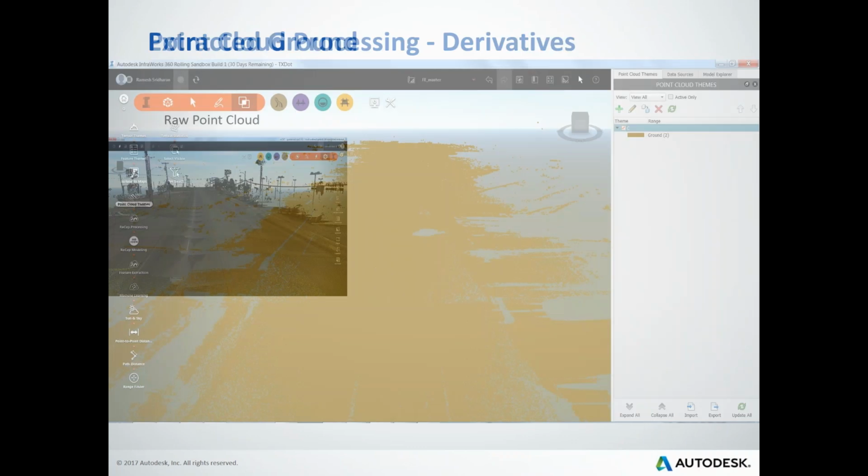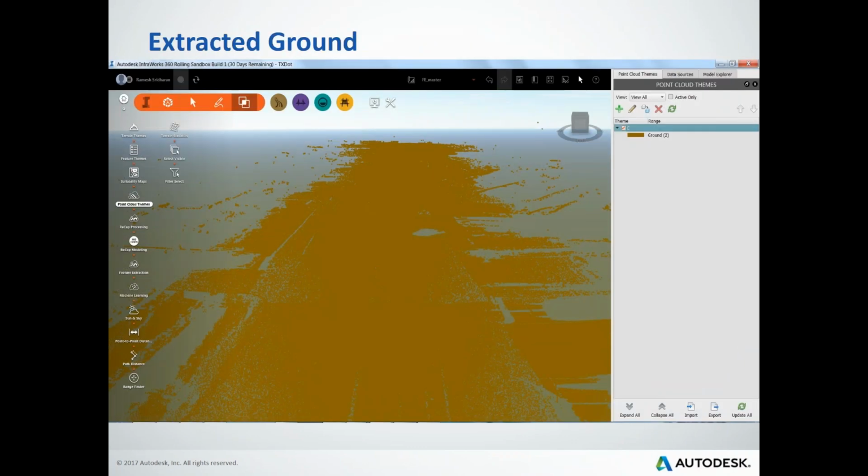And the first thing is high resolution ground. We're obviously collecting hundreds of points per square meter or so, but why waste everything? So now this ground extraction removes all the noise, anything that's not ground, and classifies the point cloud data so that users can actually use a terrain in InfraWorks to begin with.